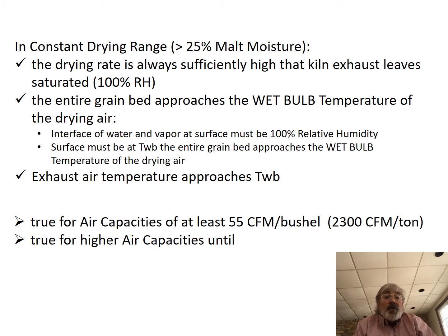And this is true for air capacities of at least 55 CFM per bushel. And it's true for higher air capacities as well, until you get to the point when you are fluidizing your bed or blowing your bed out, or in other ways creating a bypass condition where the air is not flowing through your bed but is flowing around it. All right.